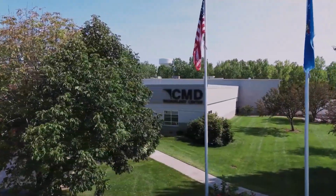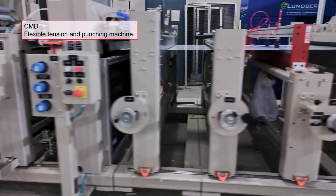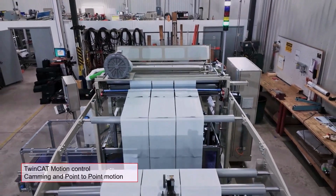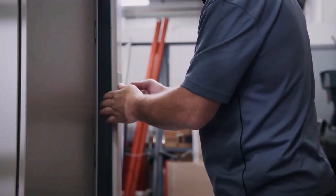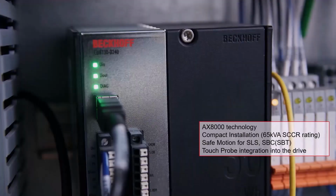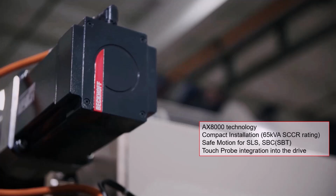Another application was with CMD. This is a flexible tension punching machine for bags. They utilize our TwinCAT motion to accomplish this with camming and point-to-point. And they utilized our AX8000 technology inside of the cabinet that makes it very, very clean. They used our high arc flash rating. They integrated touch probes directly into the drive, and the open design of the machine, they implemented safe limited speed and safe brake control with safe brake test to test out the safe brakes in the application.